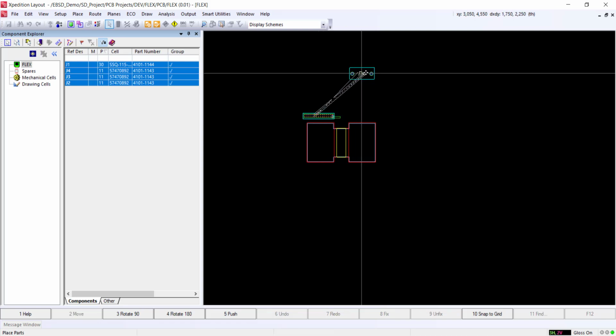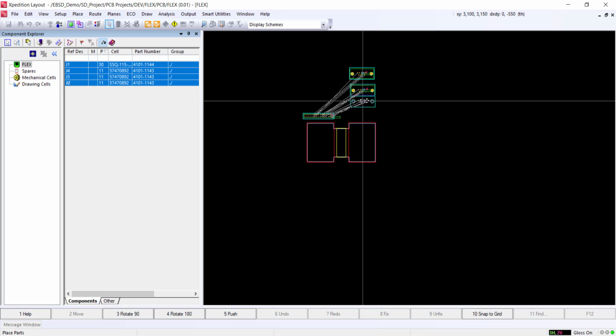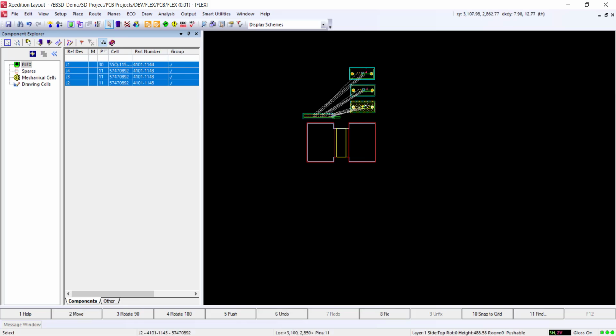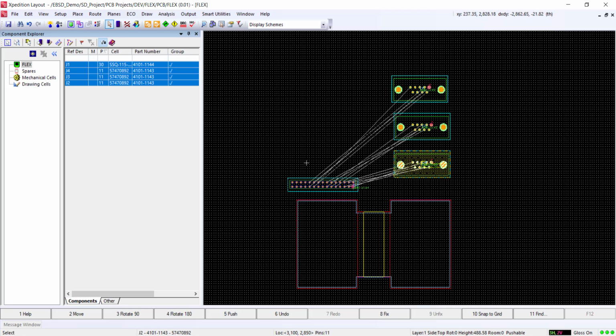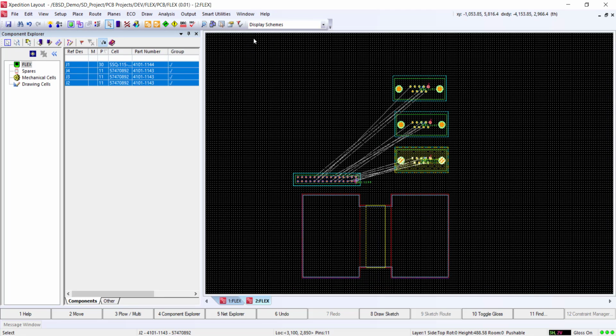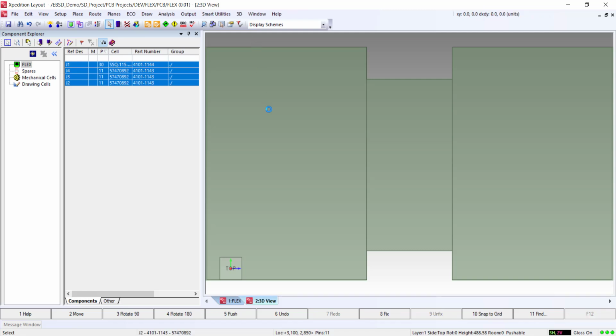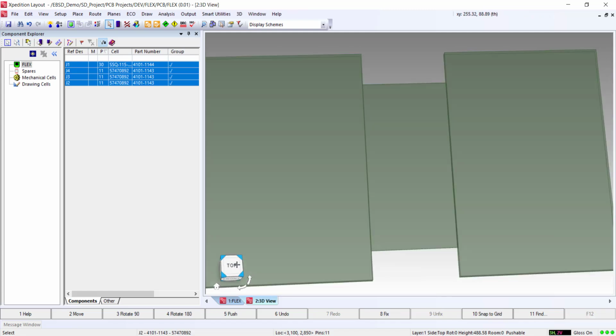The bill of materials can be directly sent to Teamcenter from EDM, but without using Teamcenter, a bill of materials can be sent as a baseline file containing the template board and all the board components. To populate this baseline file, all parts need to be placed. It does not matter where they are placed, as the mechanical designer will be redesigning the board to the required geometry. Observe the PCB in the 3D view. This is what's going to be sent to the mechanical domain.